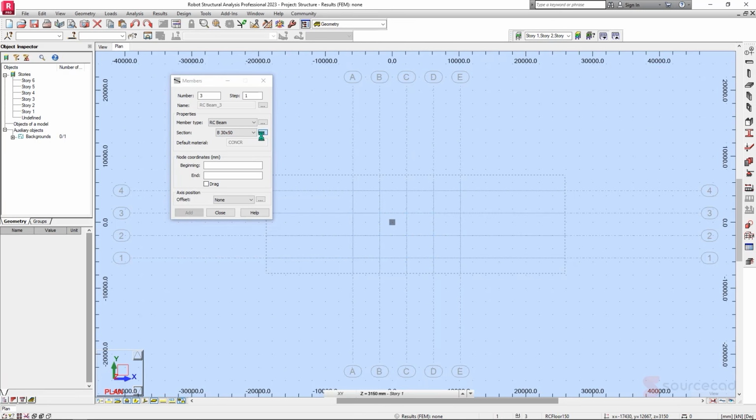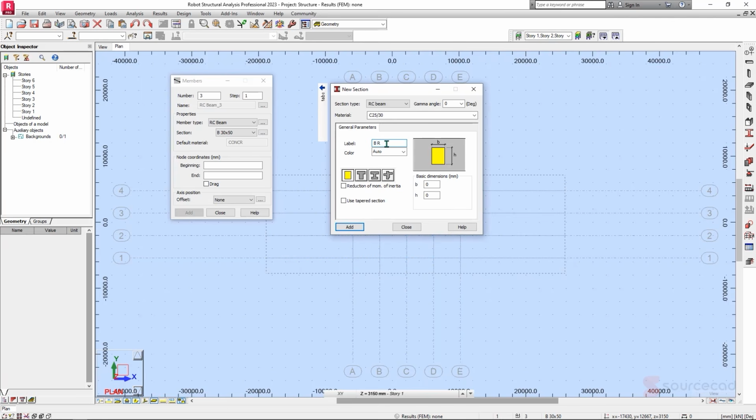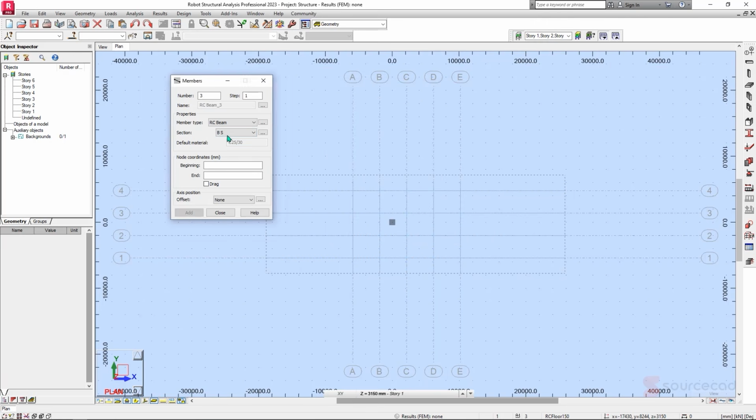So let's click on this ellipse and this window will be shown. And under this, you can even change the name to what you want. So maybe I prefer M. So I can change this to 300, the highest to 600, then click on add and it has been added. And I can change this also, let's say to S, to small, and then 300, then add. And just like that, it has been added. So that's the way we specify our section types over here.